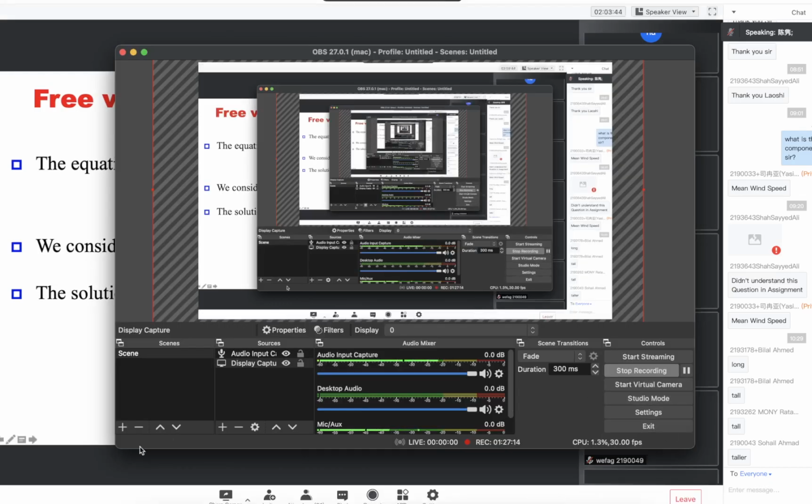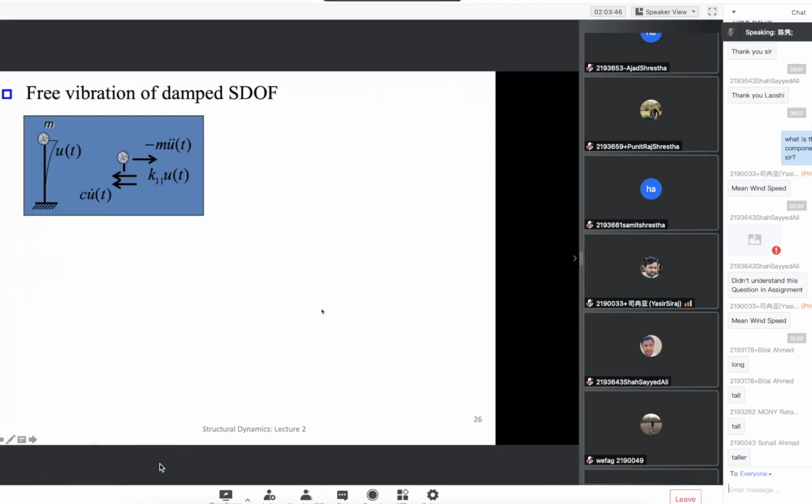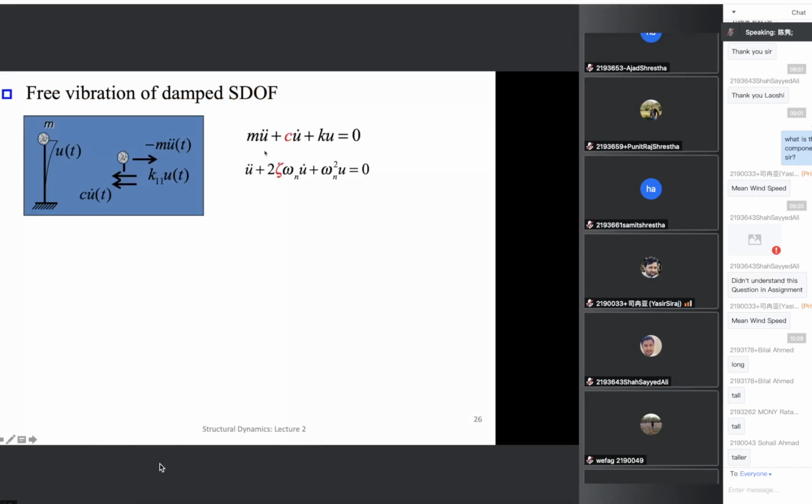The mathematical spread. And then start from here. We have another rearrangement. We need to rearrange this equation again. We divide both sides of this equation by m, so m disappears, and k over m equals omega n squared. And this part we define, we introduce a new variable here, zeta.